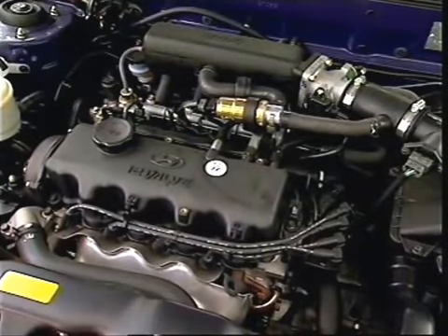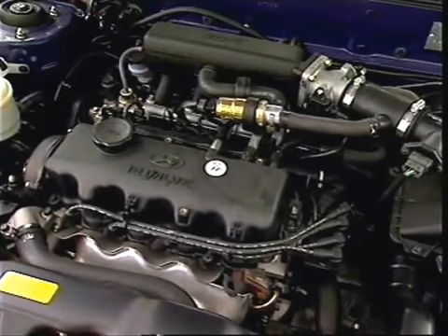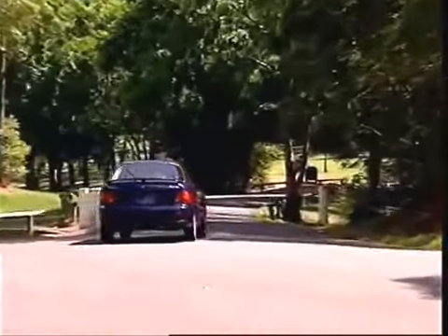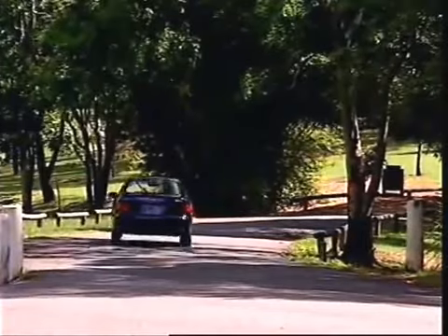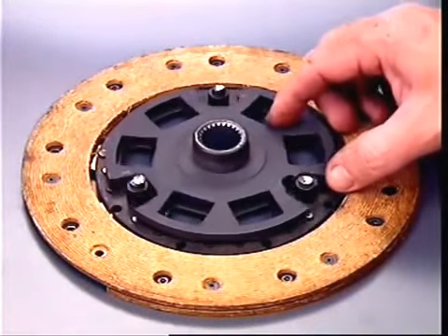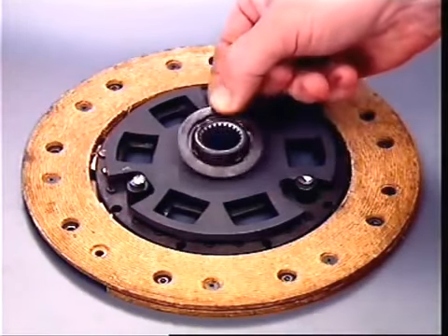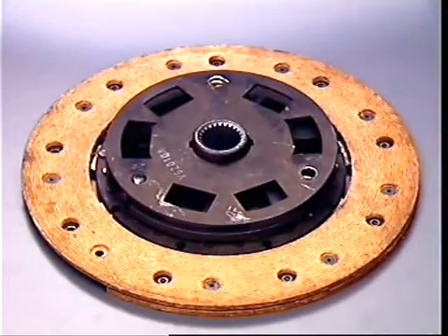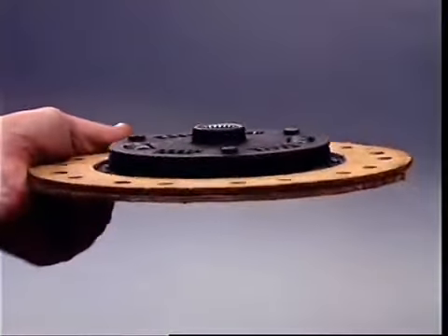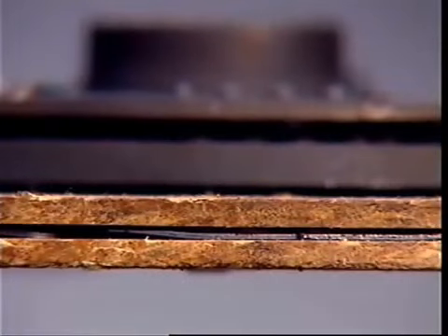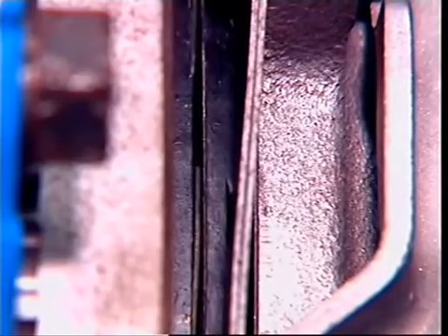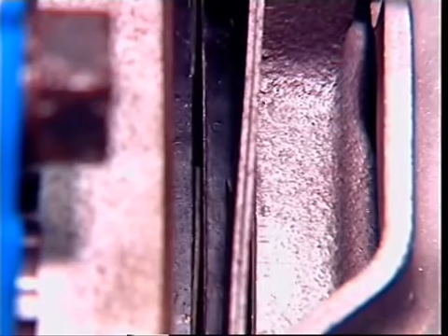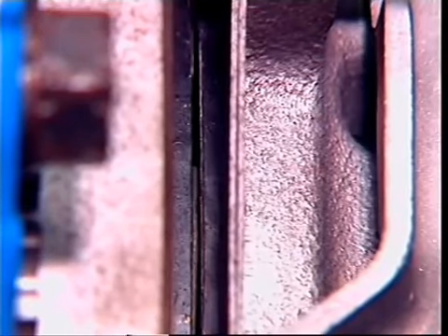This spring hub arrangement dampens torsional vibrations from the engine. It also absorbs shock loads imposed on the driveline by sudden or violent clutch engagement. Stops limit the radial movement of the hub against the spring force. A molded friction washer between the hub and spring retaining plate also acts as a dampener. The waved spring steel segments cause the facings to spread slightly when the clutch is disengaged, then compress as it is engaged. This has a cushioning effect and provides smooth engagement.